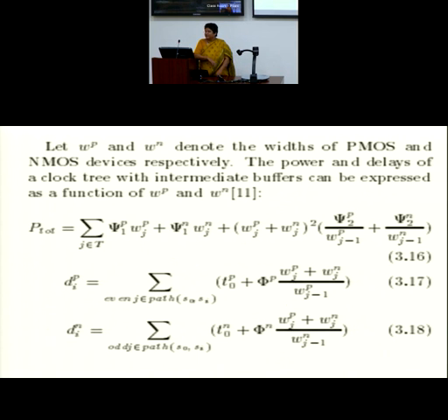From S0 to Si and S0 to Sj, the signal has to do 3 things. Design a CDN such that the signal takes minimum time to reach from source to destination, in both the paths. And also, the skew between the 2 destination points is within permissible limits, and while maintaining these 2, the power consumption is the minimum possible. So you can put more constraints. You can design it like a mathematical problem which has to be solved within constraints, an optimization problem.